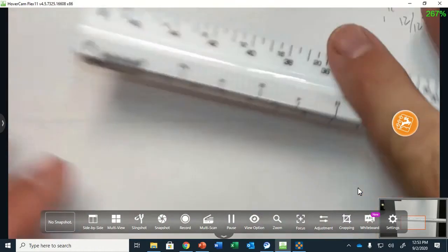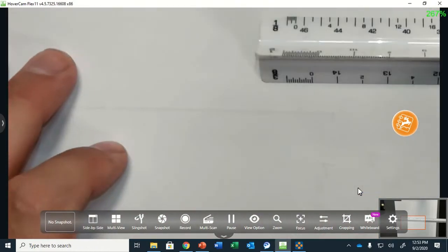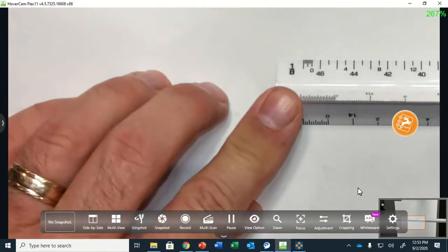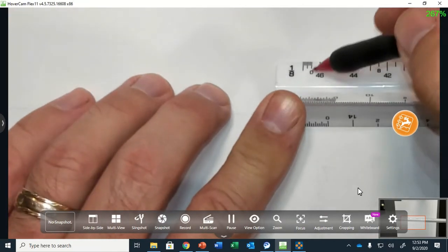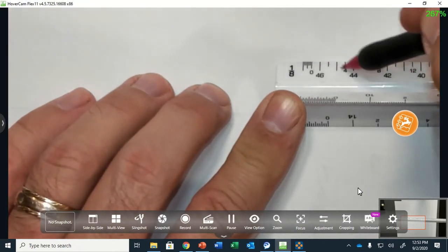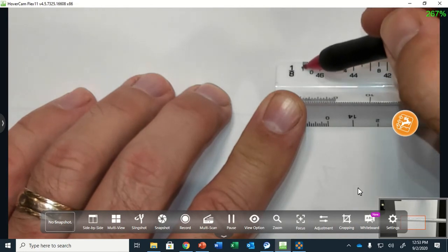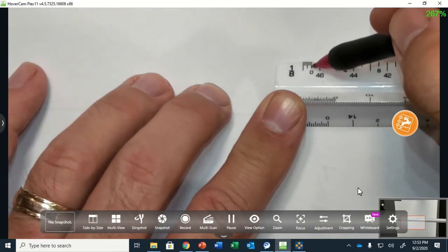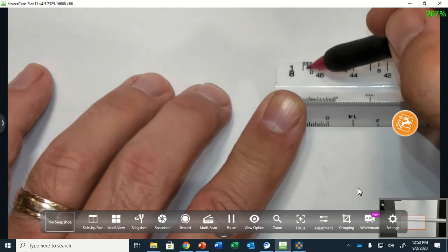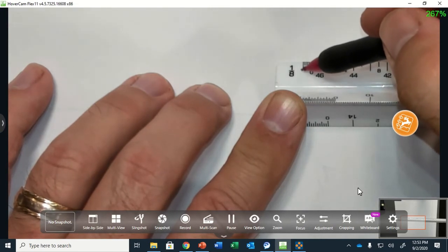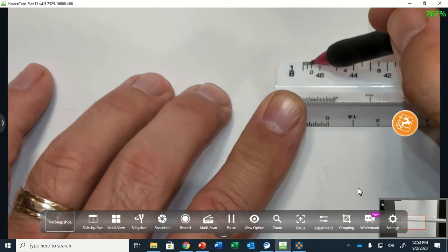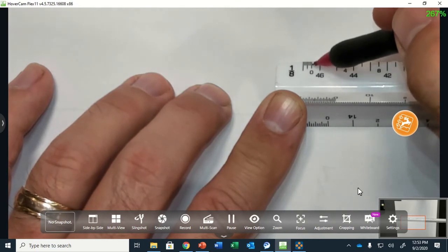Okay, let's do 1/8 inch. So if I slide this over, here's 1/8 inch. Okay, again, 0, 1, 2, 3, 4. 4 feet, okay? So from here to here, again, we're squishing 12 inches into here. So that's the 6 inch mark, right? Okay, so 12, that's 6, 4, 2, 0, right? So you just figure out, each tick mark is actually worth 2 inches.